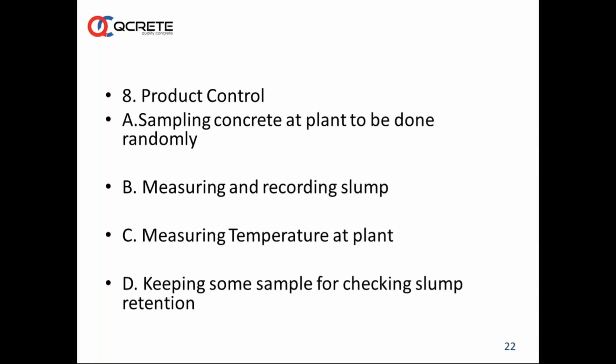The temperature of concrete at site may be 27 or 28 as per specifications, especially for mass foundations. Temperature is a very essential property, where we have to take care of heat build-up, and for controlling cracks and evaporation losses, temperature is very important. We also need to be very careful about temperature when we are doing high cement content concrete mixes. If the concrete is M40 or M50 where the cementitious content may be more than 450, say for example 430 plus 20 kg microsilica or something like that, the heat of hydration and the reactions go faster within the body of concrete in the initial stages, the evaporation losses will be more, so the temperature has to be controlled.